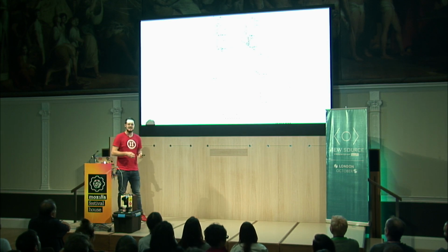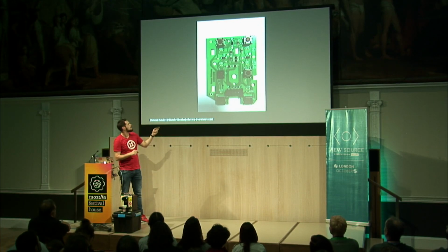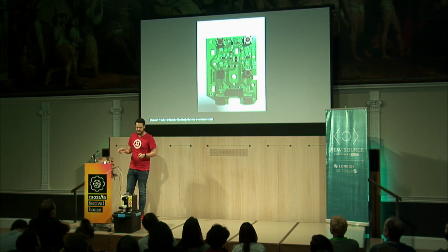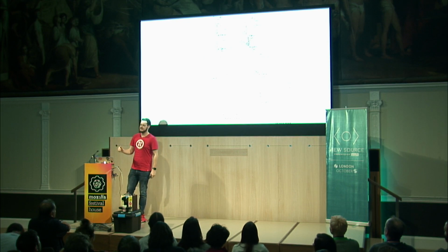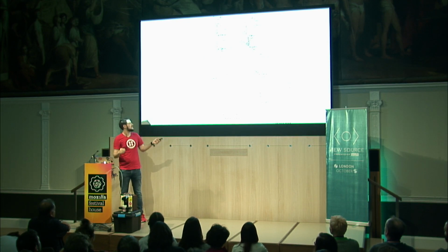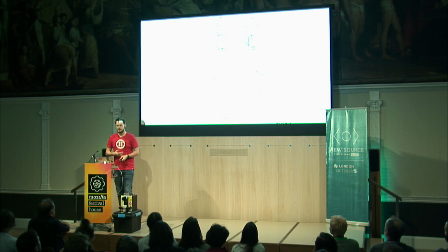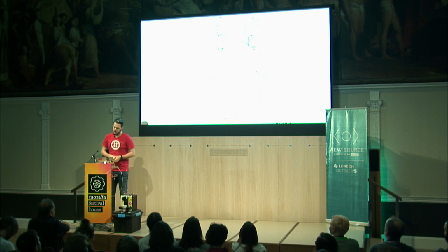Basically, we went along the lines you can see on the board and always measured the resistance between 2 points. If it was 0, that meant it was indeed connected, so we didn't screw up the path. Based on that, we created this diagram. The only thing we dropped was everything that looked like a resistor, because it didn't alter the behavior of what we wanted to achieve.